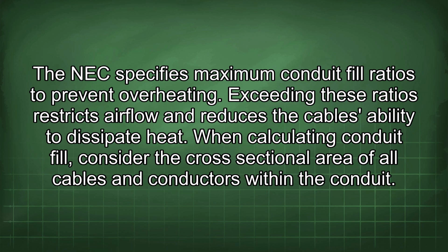Exceeding these ratios restricts airflow and reduces the cable's ability to dissipate heat. When calculating conduit fill, consider the cross-sectional area of all cables and conductors within the conduit.